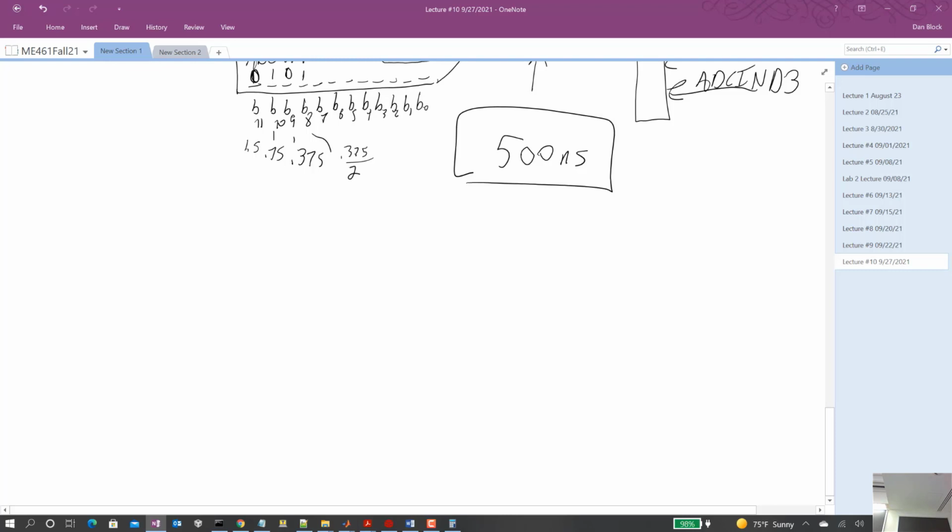If you were a little lackadaisical in where you route your signals on your board, maybe you'd want to sample in a weird order. But it makes so much more sense just to sample pin ADC-in D0, then D1, then D2, then D3, so your code doesn't get confusing. But the sequencer allows you to do it in whatever order you want.